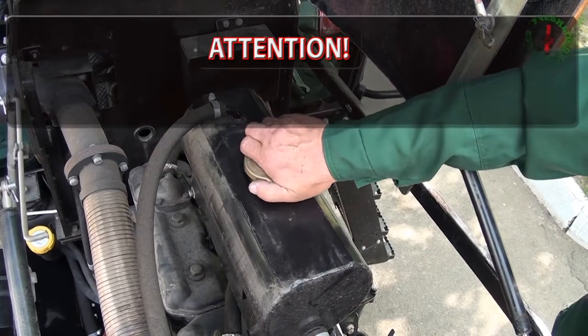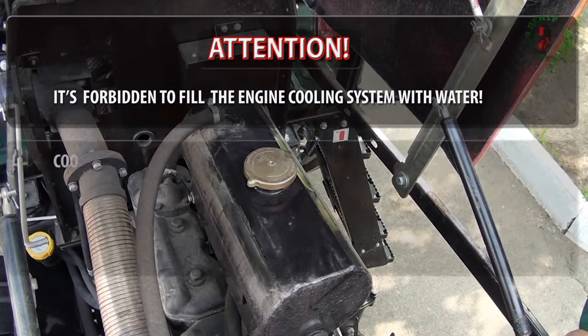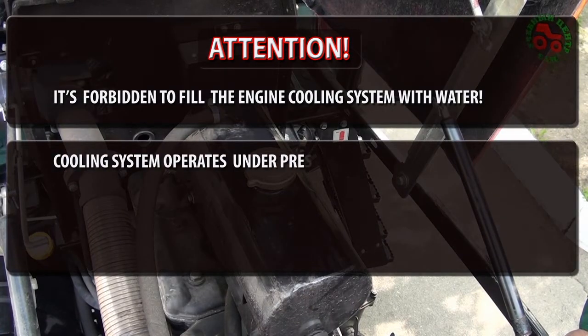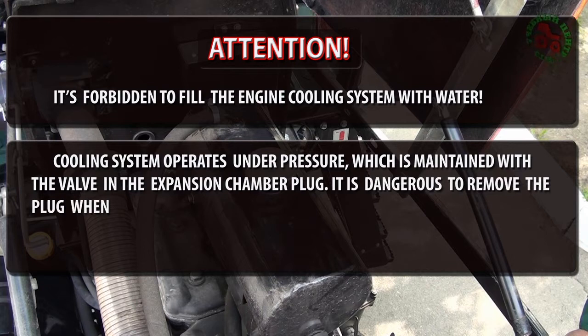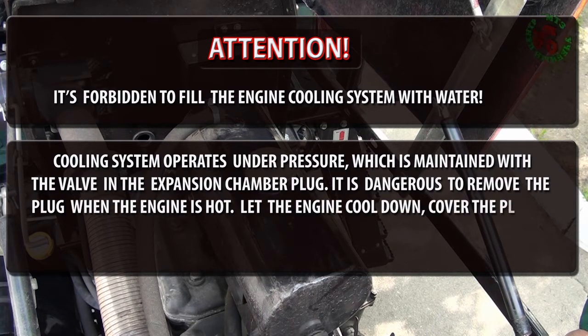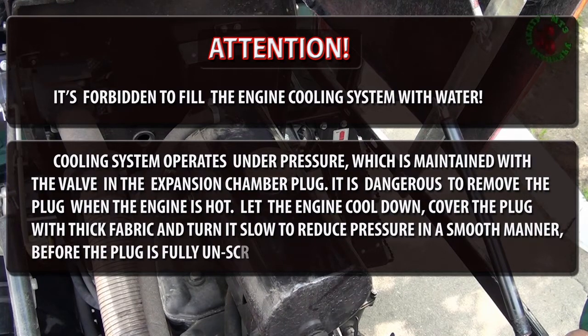Attention! It's forbidden to fill the engine cooling system with water. The cooling system operates under pressure, which is maintained by the valve in the expansion chamber plug. It's dangerous to remove the plug when the engine is hot. Let the engine cool down, cover the plug with thick fabric and turn it slowly, to reduce pressure in a smooth manner, before the plug is fully unscrewed.